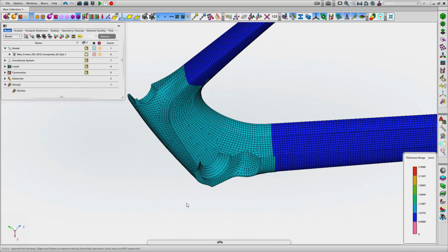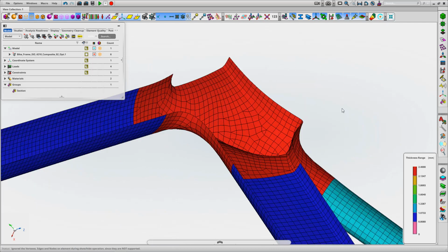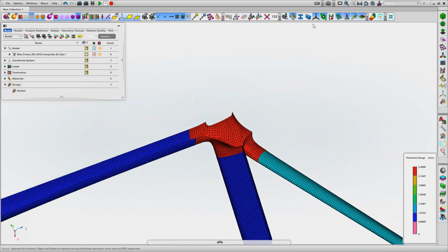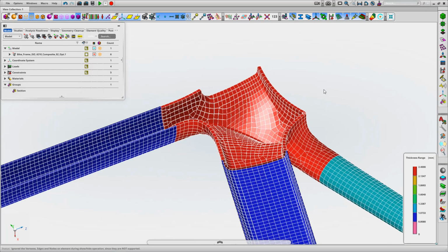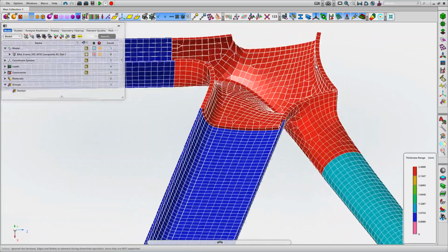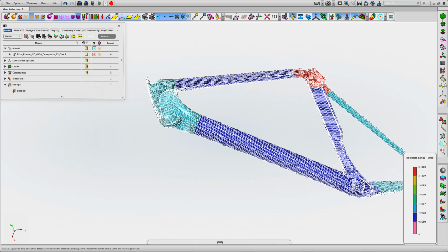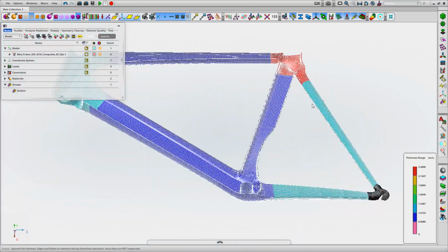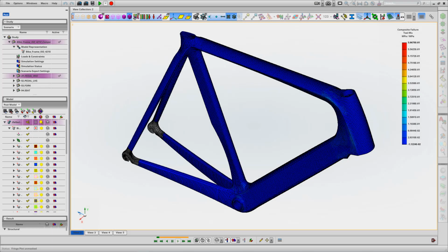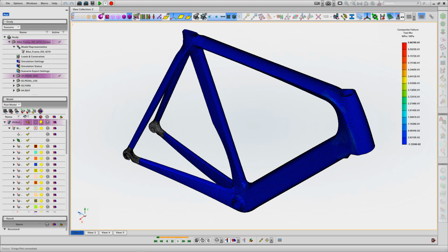If we were to look at a section view, again with our thicknesses shown, the head tube and the seat junction are doing a lot of the work for these load cases. We've hidden some of the internal structure here, specifically at the seat tube interface, but we can see the change in thickness. So we can bring in lots of Apex advantages here to maybe develop our drape ply definitions and also our ply drop-offs, and then ultimately we can look at our structural response. So we've got much reduced weights for better structural behavior.